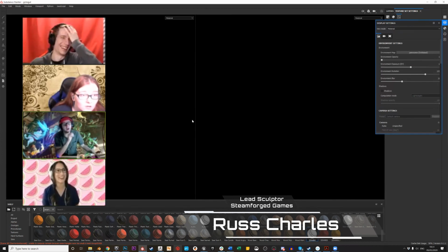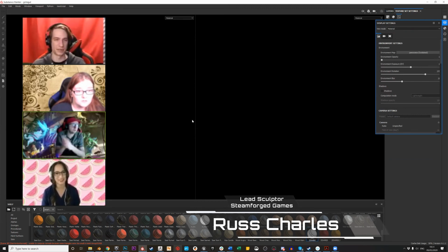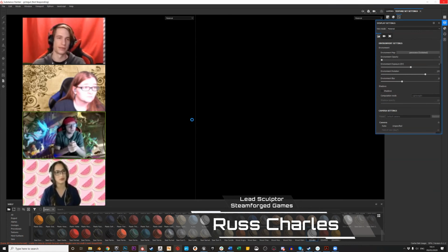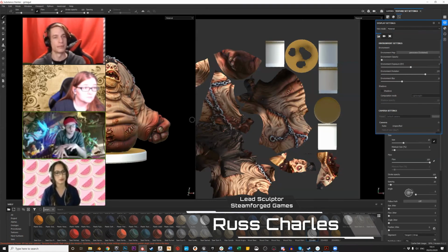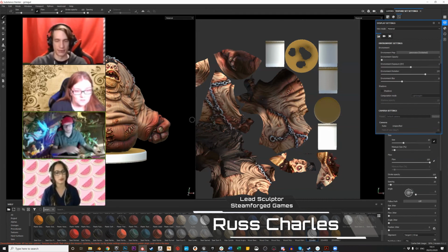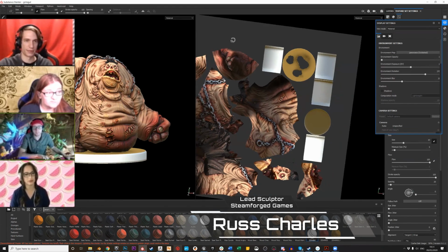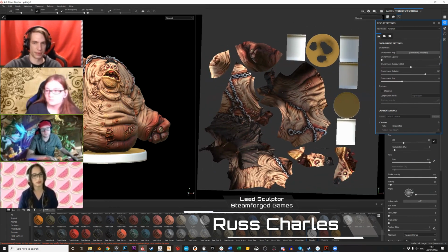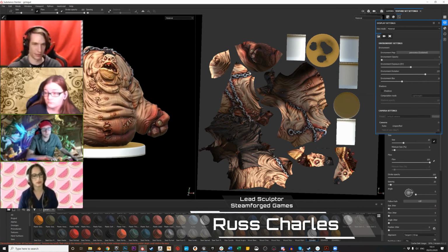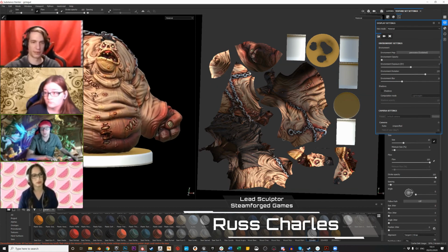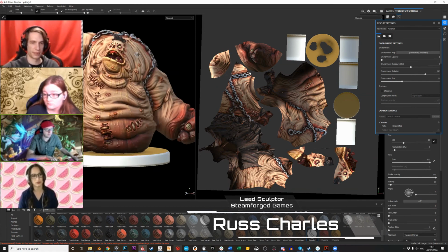Probably better. The way I always describe it to people is like when you buy a cereal box, obviously it comes shaped like a box with cereal in, but when it's printed in the factory, that box is folded out flat so that the printer can print the surface onto the box. A UV map, in fact, here we go, we can see one. A UV map is just taking the surface of the model and unwrapping it flat in a way the computer can understand, so that color and texture information can be applied, and then the computer takes that and wraps it back around the 3D model.